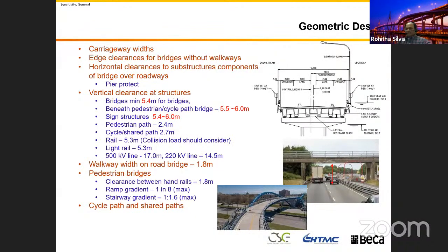Then this bridge is not going to be serviceable. Therefore, you need to make sure your bridge has a minimum vertical clearance if you are building it above a road. There are minimum requirements, which depend on the road agency and the country, with different standards giving different numbers.